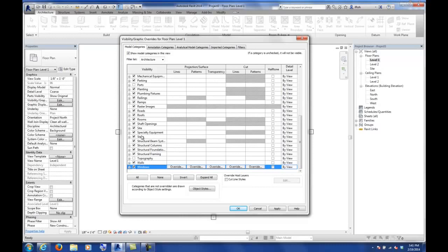Working in categories also allows you to schedule components correctly. When you get into scheduling, which we did at the end of last class where we did those mass floors, that's because mass floors are on a mass floor category. So the categories are very important, and that eventually gets into further bits and pieces in Revit where you can not only schedule, but also turn things on and off, and change your visibility.